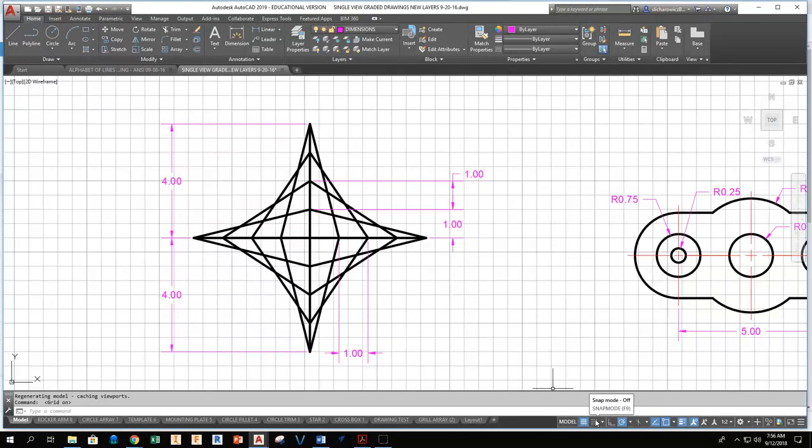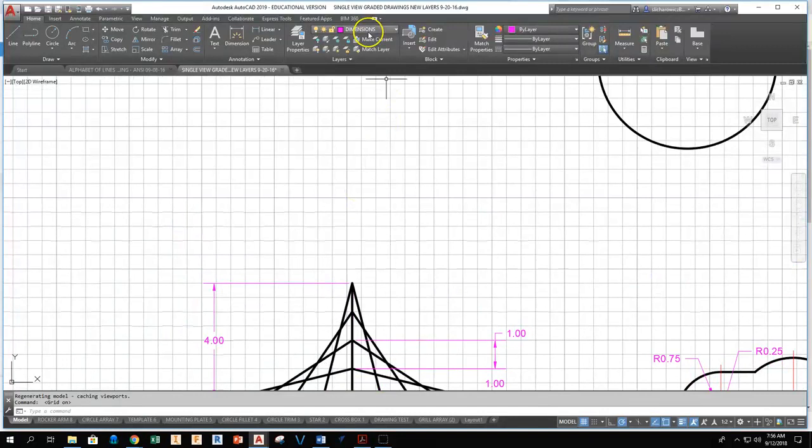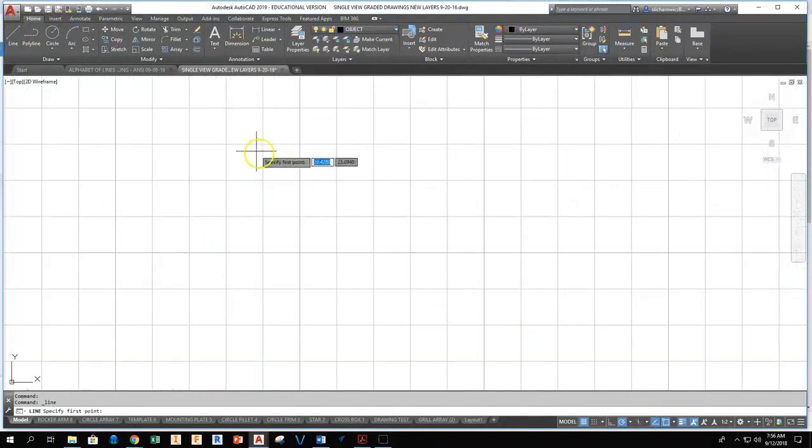Now the snap mode is different than the OSnap tool. Everything we've done so far in here works with the OSnap tool, or the object snap tool. That's where when we draw a line, I'm going to use my object line, I'm going to grab my line, I'm not actually linking to my grid, I'm just drawing a line from point to point, and then if I grab another line, it actually snaps to the end of a line. You guys know that must be set up, and you must have your OSnaps on so that it is linked. You can't zoom in close and get it close.